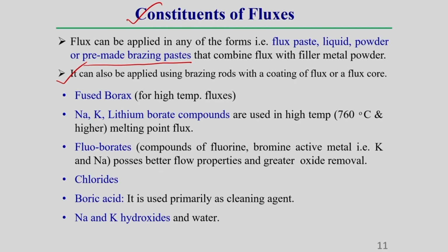What I am telling, understand? That means this is a filler wire which we are going to use to join the base material. So, what we can do? We can use this flux over the surface, that means a layer of paint type of thing we can provide over the surface of this filler wire, or we can make a hollow cylindrical filler wire.